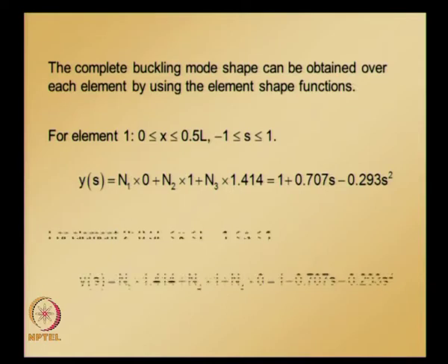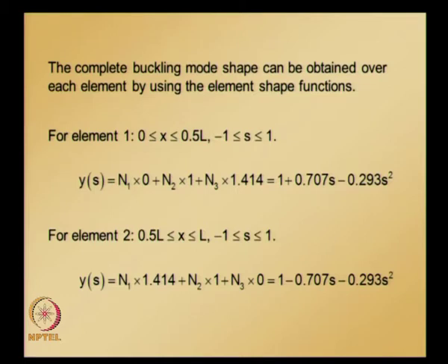Similarly for element 2, x goes from 0.5 L to L, s goes from -1 to 1, substituting the shape functions N1 y3, N2 y4, N3 y5, we get this equation.